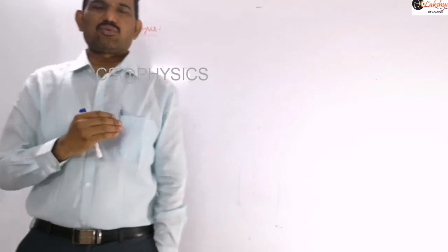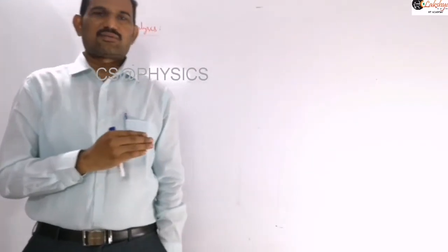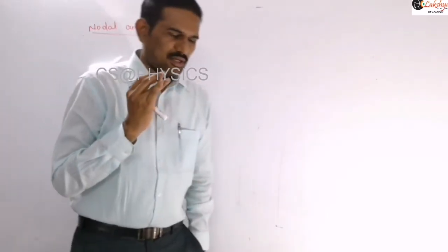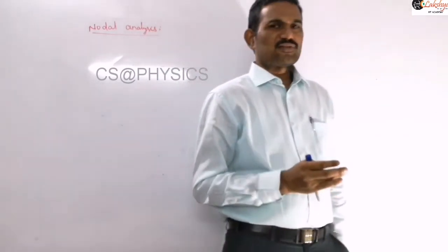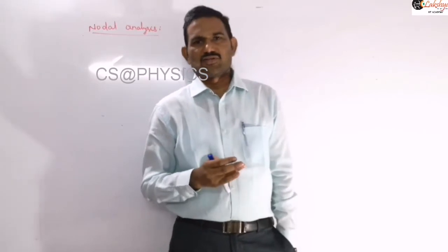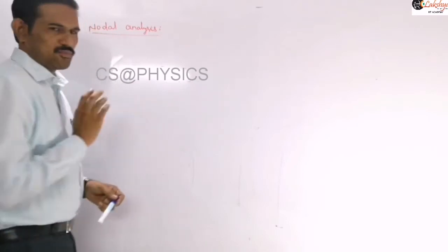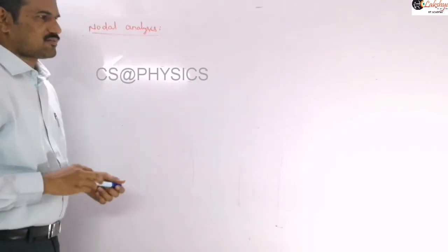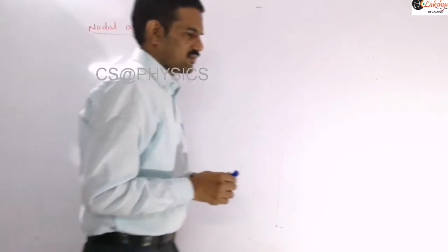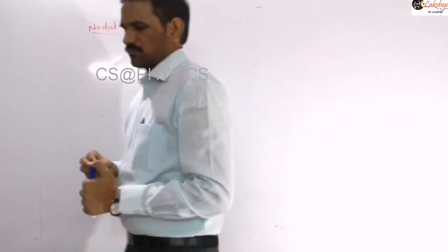Then by solving those equations you will get the potential values. From that you can calculate either potential differences, or effective capacitance, or charges at the different junctions, right? Now let us apply this to the same previous problem, but first just to mention the procedure generally for applying this nodal method, briefly. In nodal method,